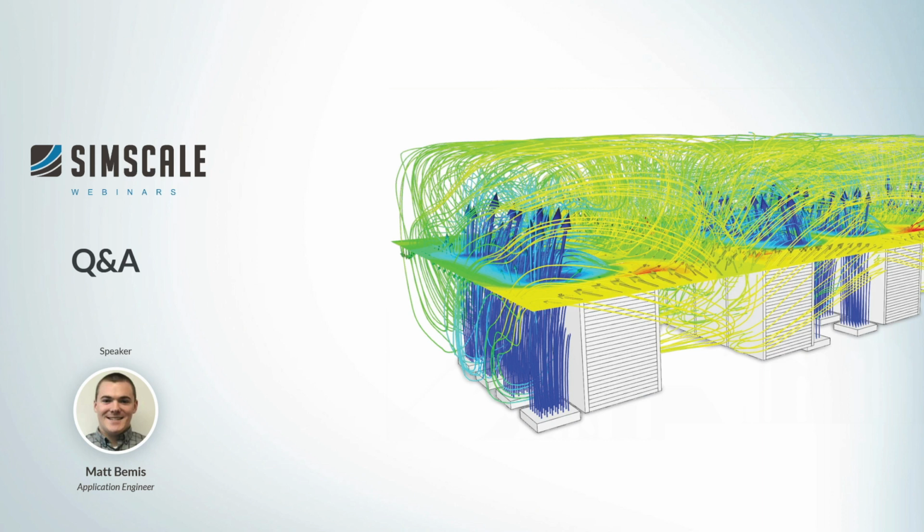So before we dive into Q&A, I would like to just kind of recap on what I showed you today. We had a look at a classic raised floor data center, which has downflow CRAC units and a room return. We had some issues on ASHRAE conformance at the rack inlet temperatures. Specifically, the racks closest to the CRAC units were a little on the warm side, and instead of just driving down the supply temperature or putting more air into the room, both of those are expensive.